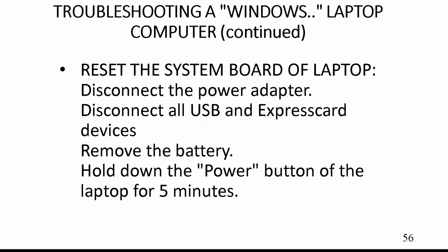This procedure has been built into every laptop ever manufactured, including most of the Macs. And if you do it, what you're doing is you're bleeding off residual voltage in some of the chips and some of the capacitors inside the system board of the laptop. And oftentimes that fixes whatever problem you had with it. Now, with desktops, you don't have to hold down the button. You just disconnect everything and wait 5 minutes. I just had to do that with a computer of mine yesterday.